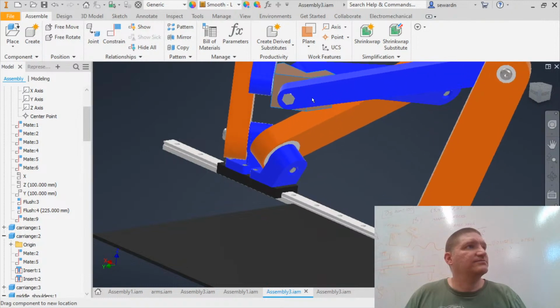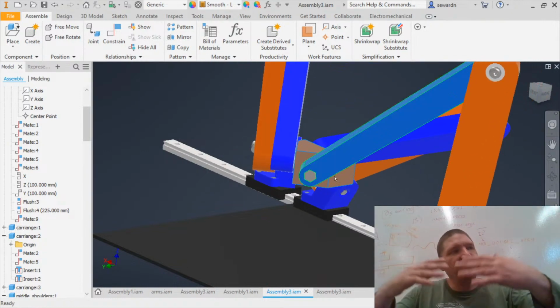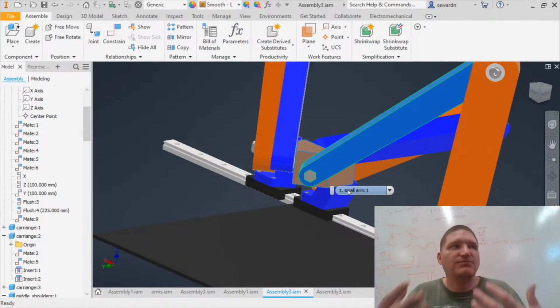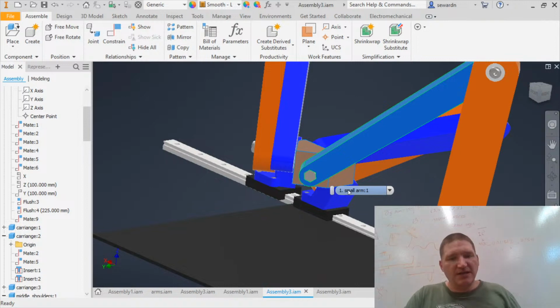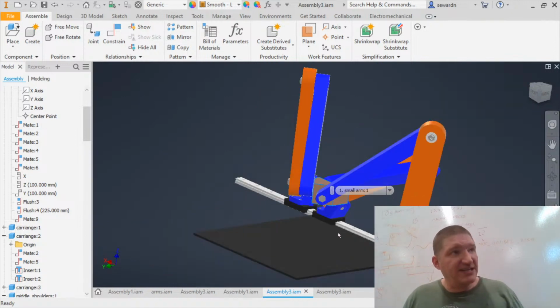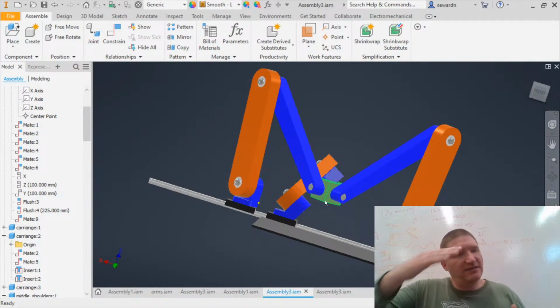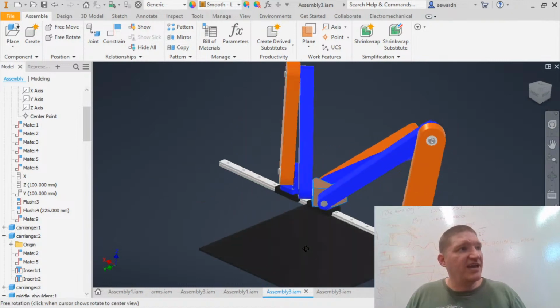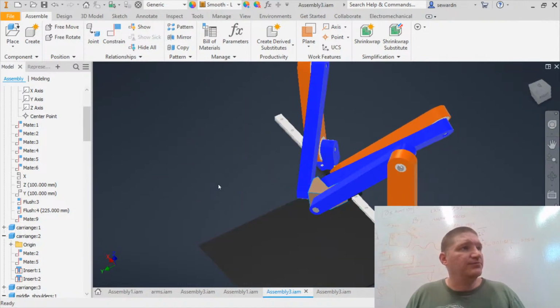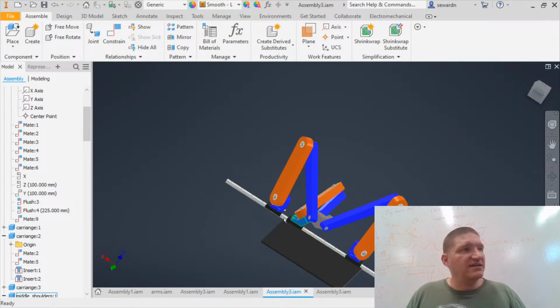So, anyways. Basically, Z is 0 close to the rail, but you don't want to print close to the rail. As you move farther away from the rail, you go up and up and up. And the Z increases quite fast because I picked like a 30-degree angle, so it's a pretty steep incline there. So you actually have a fairly usable print area, but there's a lot of constraints on this.